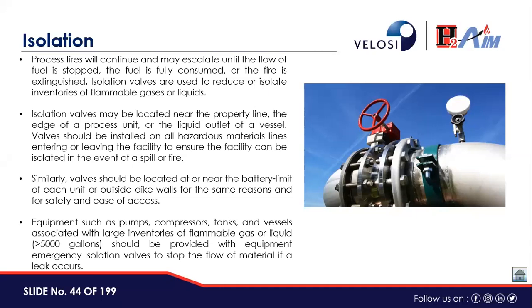As I read the content of the presentation, if you see a P&ID, that makes it easier. There are various kinds of isolation valves and isolation philosophy: positive isolation, like two isolation valves with bleed or drain, or one isolation valve with a spectacle blind. Boundary limits are followed between plants and within the plants. Various kinds of valves are used as part of process plant design, as a P&ID part.